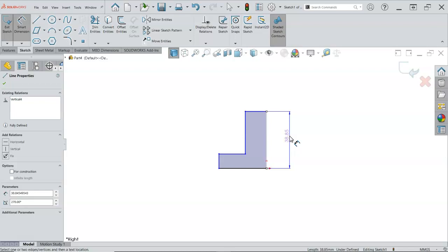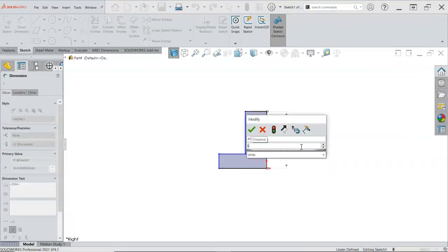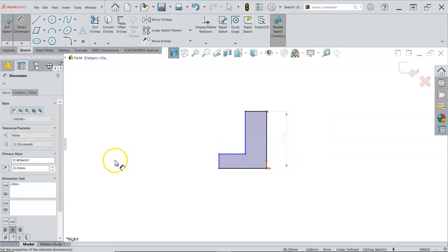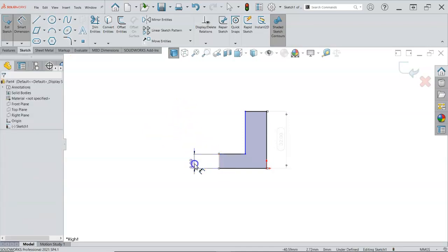So the first one that I pick is actually a missing dimension on the print. So that being the case, we know that we have 8, probably a 12 and a 12. So maybe we'll go for 32. That being the case, this would be one of those that I want to turn into an inspection dimension. I'm not sure. I want to come back to those numbers to be able to verify that geometry. So we'll go with the 8.